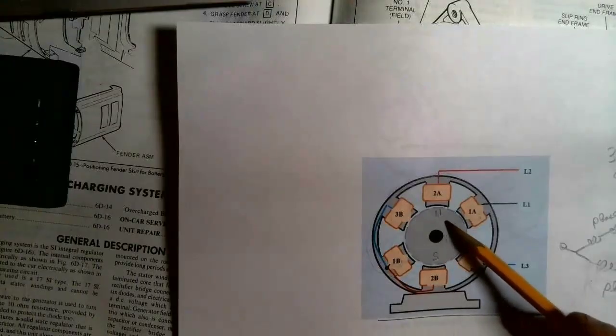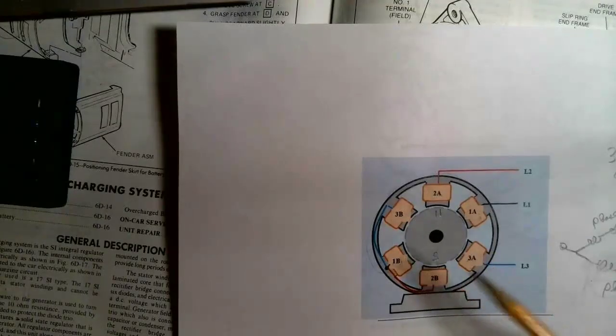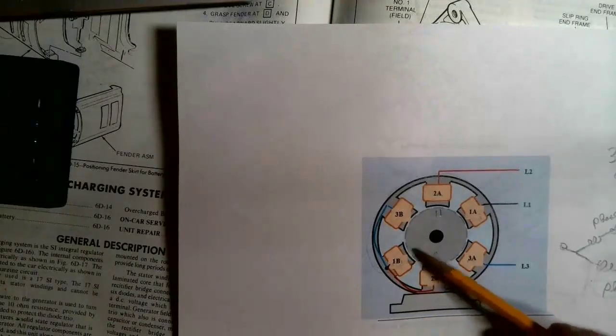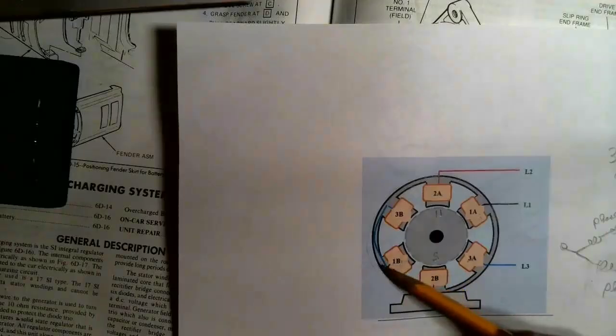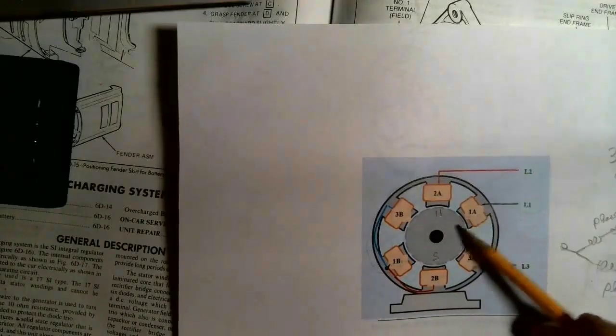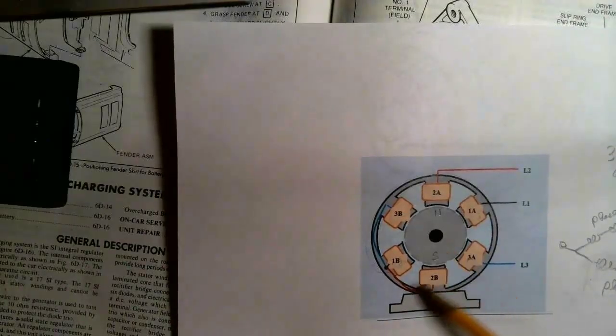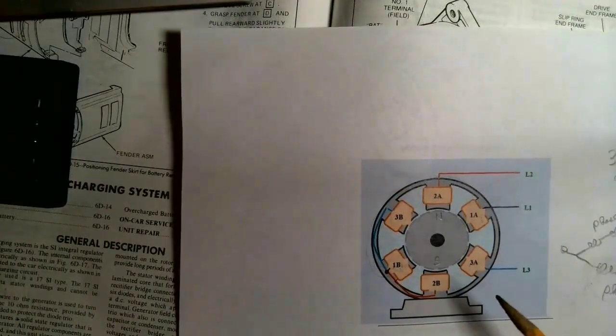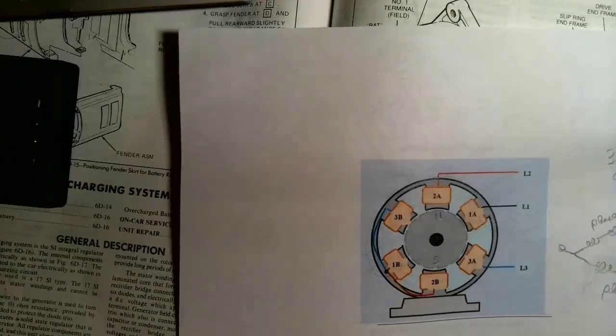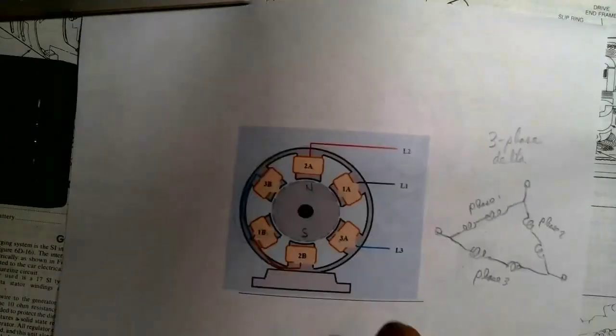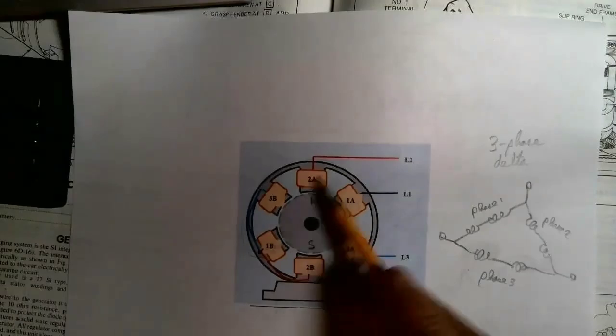And then when the rotor has rotated 180 degrees, the flux travels the other direction, first through this coil, and then around this way back to the south through this coil. But that happens in all of these six coils here, just 120 degrees out of phase with each other because of their different displacements around the perimeter of the stator frame. And these three phases, there's six coils here.